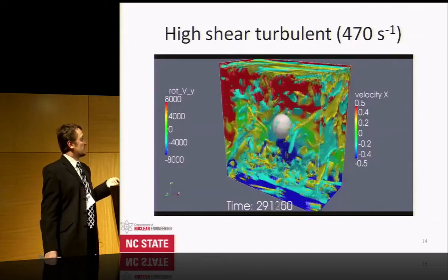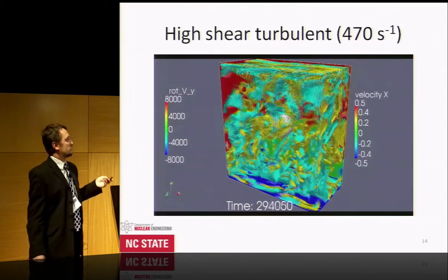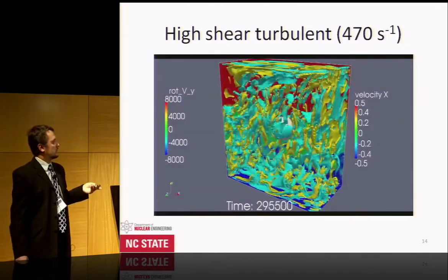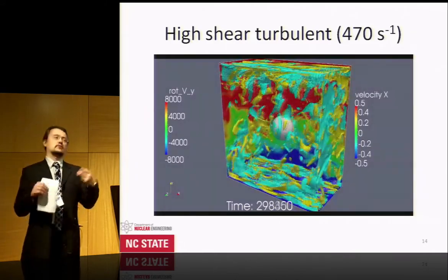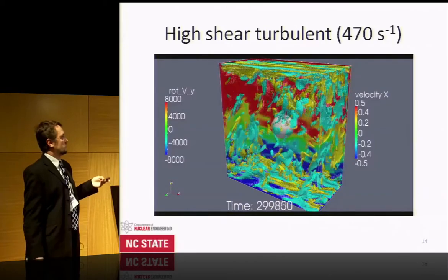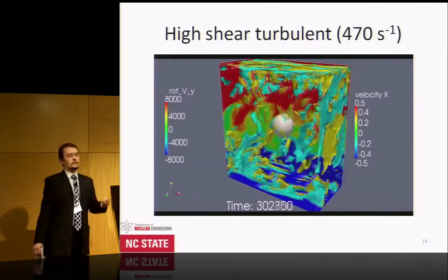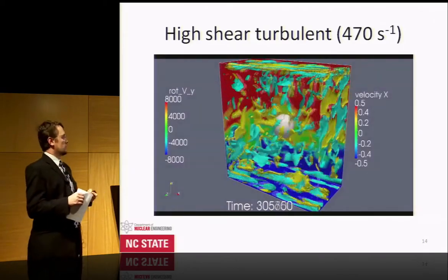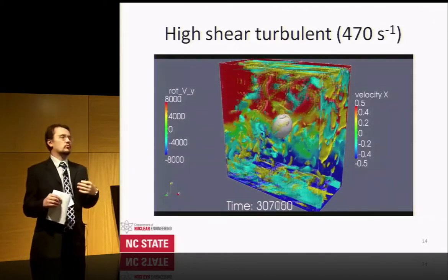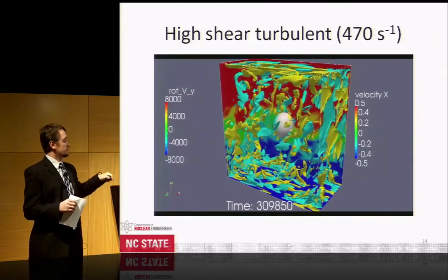Now this is getting a little bit more interesting. It's a more expensive and more challenging simulation, where you're actually feeding single phase turbulence through boundary conditions, resolving those turbulent eddies acting on that bubble. Again, you're keeping it steady, also challenging, and the conditions are getting similar to what nuclear reactor cores are experiencing, but still we keep the Reynolds number pretty low because it's too expensive to fully resolve it, and we'll get to it in a moment.